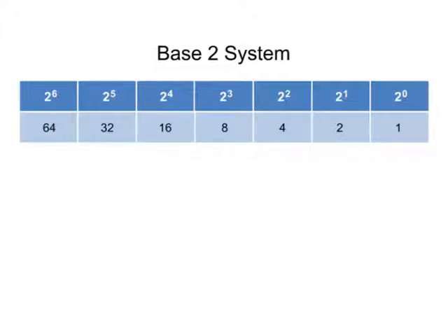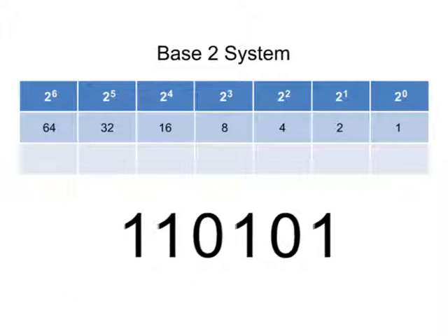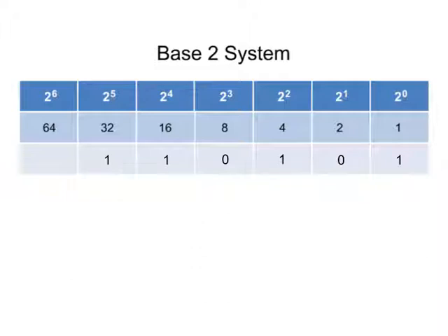When you work with digital equipment, converting between the binary and decimal numbering systems is often required. Let's take the binary number 110101 and convert it to a decimal number equivalent. We will add together all the decimal number place values converted from a binary string. Thus, moving from right to left, we encounter a 1. Multiply it by its binary place value of 1 to give 1.